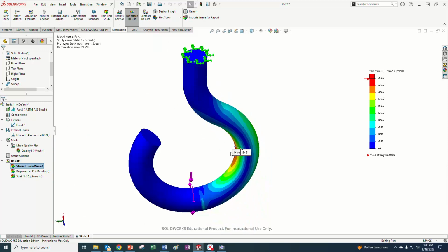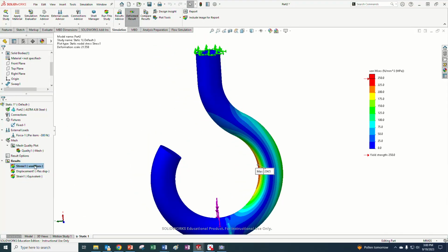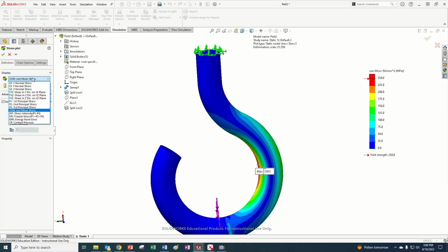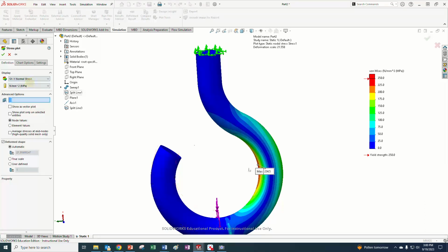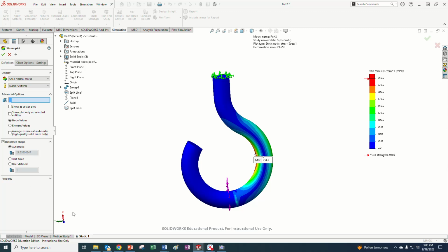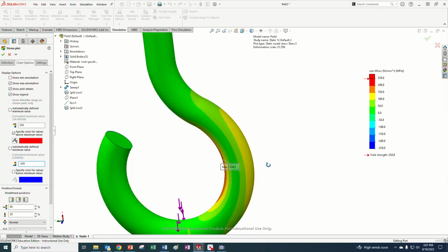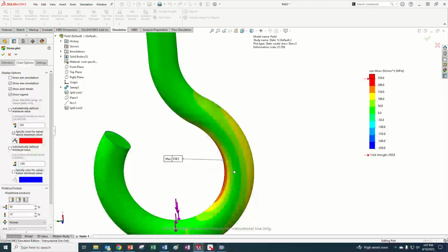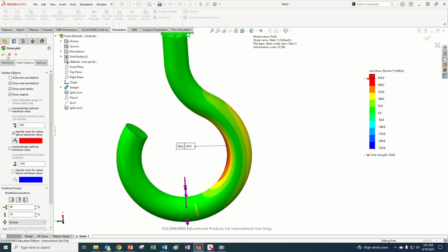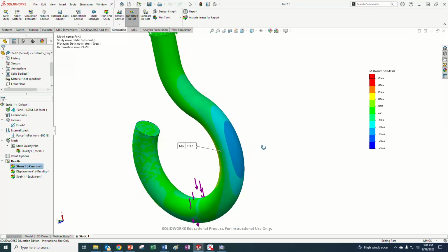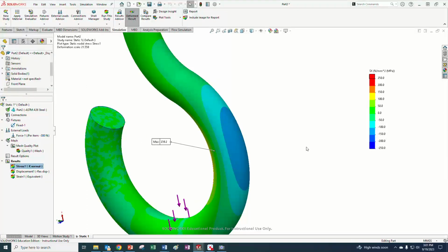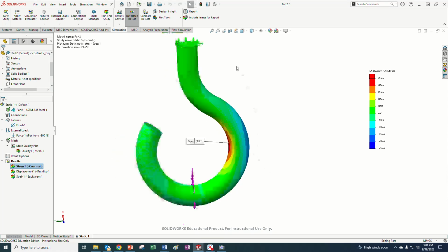We could also, right, this is all von Mises stress. Let's go ahead and change the stress, edit definition, to being the normal stress in the x direction, right? So the x direction is upwards from this coordinate system, you can see down here. And I will change the chart options. So now let's go to negative 250, right there. Not nearly as much fun, right? Because the negative doesn't get into the plotting of the thing, but now you can see it get a little of the blue, so it gets a little down into there. See, 0 is green.